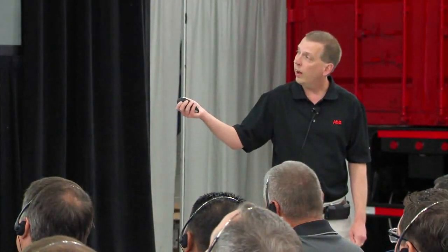So that's what both open loop sensorless and DTC sensorless control do. Now, DTC sensorless control is ABB's proprietary sensorless vector control, and it goes a step farther. It's a pretty complex conversation, but in a nutshell, what it does for most people is that you can get 100% torque at zero speed with this type of control without an encoder.